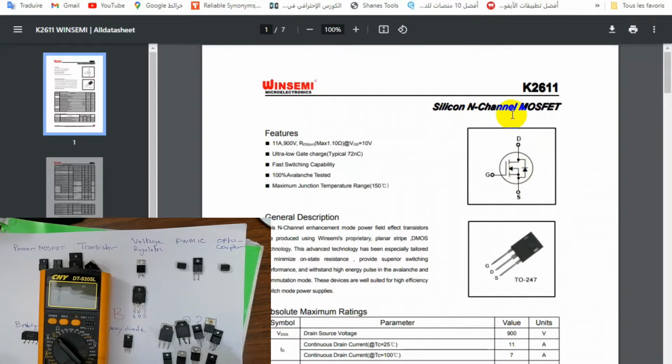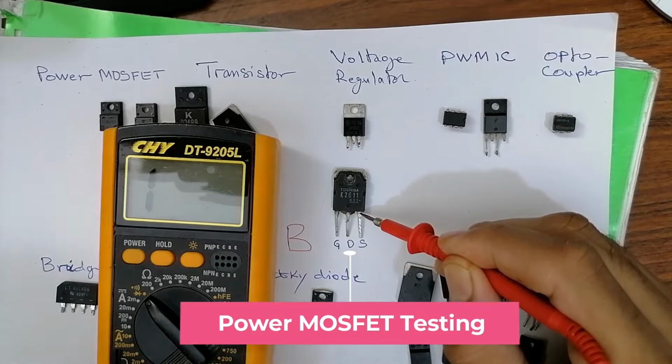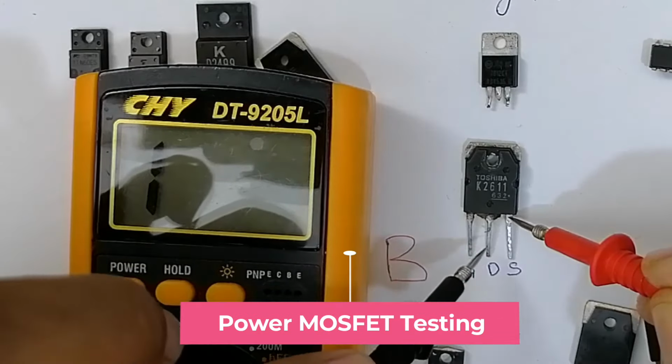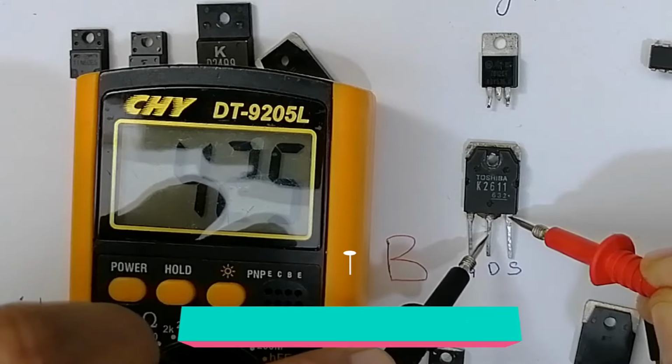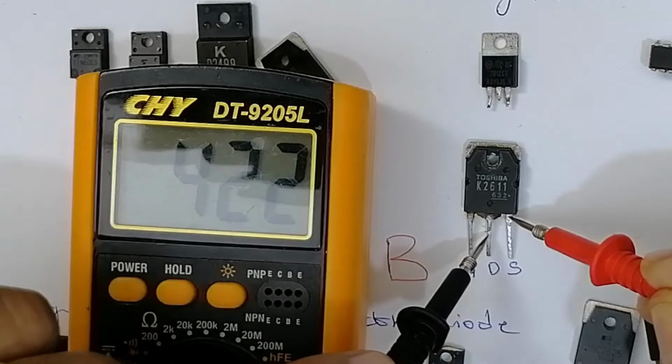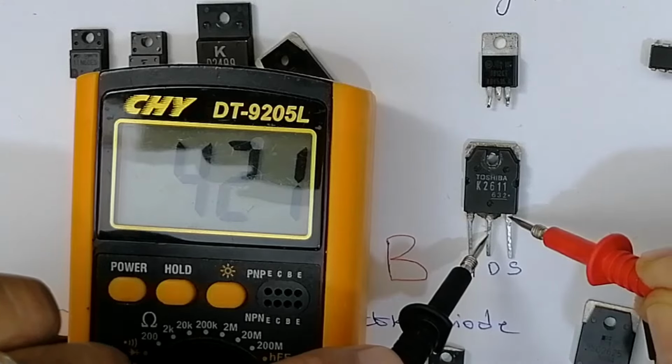So let's put the red probe in the source, as you can see here, and the black probe in the drain. I should get a reading about 400, 500, 600. As you can see in the multimeter, I get the reading because this is N-channel MOSFET.